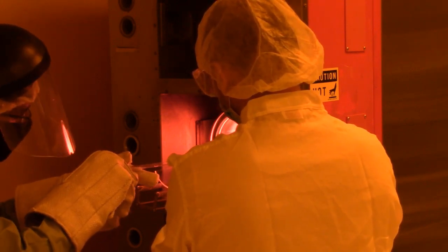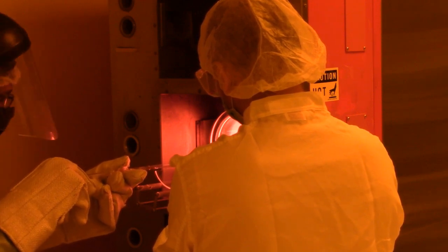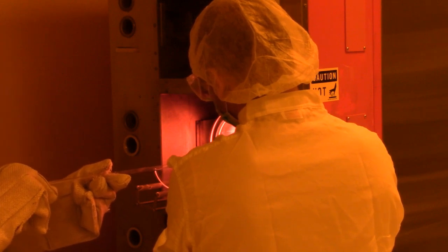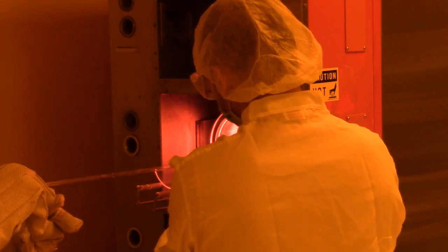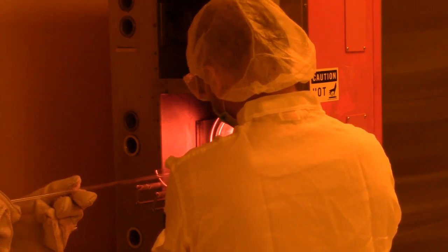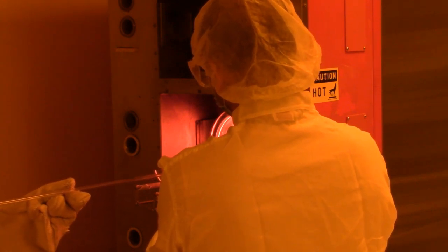One important point to keep in mind while taking out the wafers is to make sure that you don't take them out real fast. If you expose them to room temperature immediately once they're coming from 1100 C, a huge temperature gradient can crack the wafers. It's very important to make sure that you pull them out as slowly as possible.